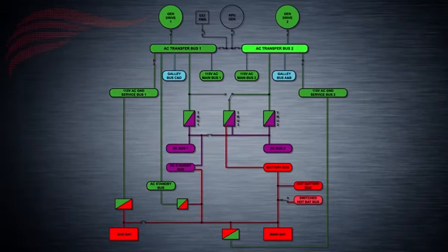Similarly, AC transfer bus 2 also subdivides into the following buses: AC main bus 2, AC ground service bus 2, galley bus A and B. AC transfer bus 2 also supplies energy to the DC bus 2 with another transformer rectifier. Notice that the AC standby bus is partly AC powered only by AC transfer bus 1, but it also has a part which is powered by AC current derived from the DC electric system. DC to AC conversion is achieved with an inverter and will also be discussed later on.